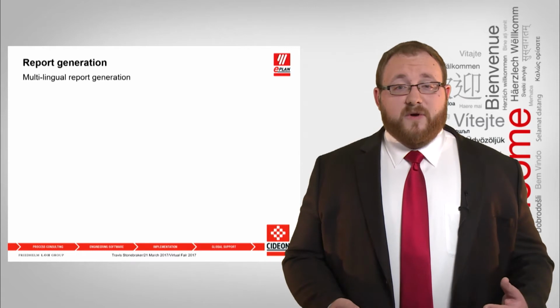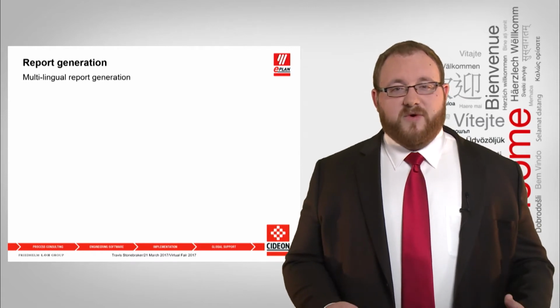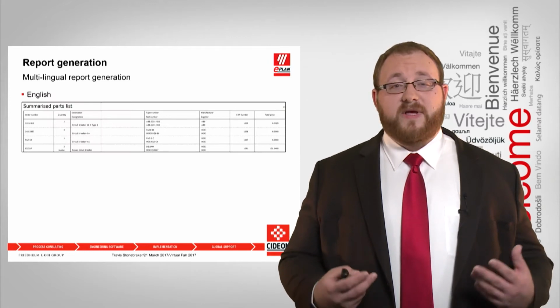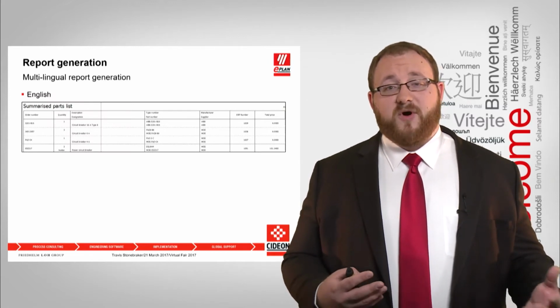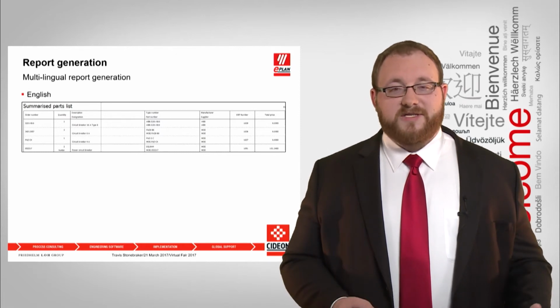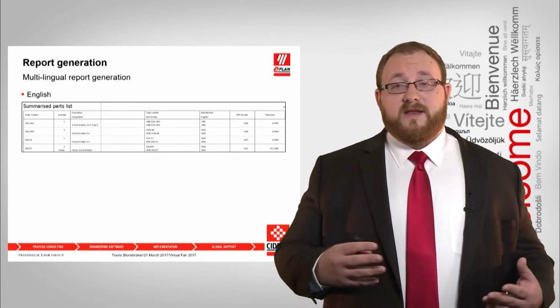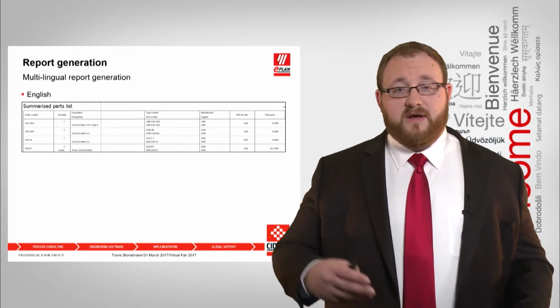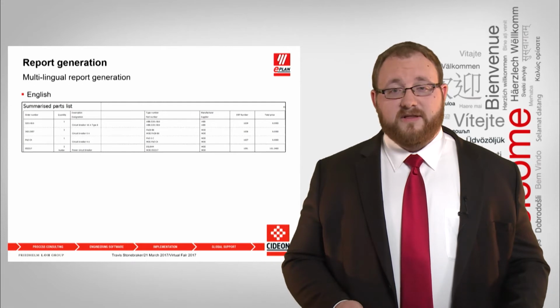So the next piece I want to go over is the report generation with the multilingual option. The very first report that I have is an actual English report. This is a parts list, or kind of a bill of material report that I had in my Eplan project. And you'll see here that the name of the report is all in English, that the column headers are all in English, the material description names are all in English.